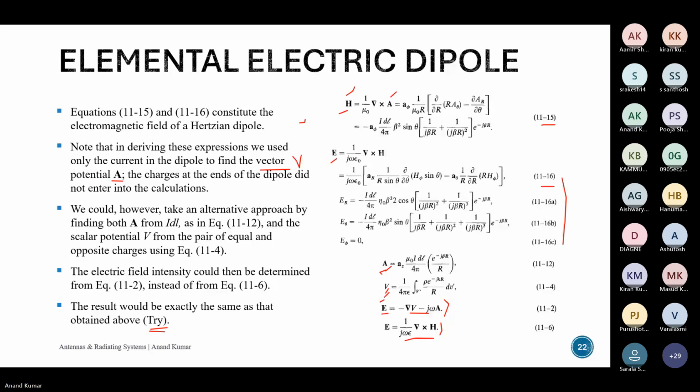They are designed to match for a wider range. Like you have a coax as your feed, which is usually 50 ohm, and then it matches throughout for all the frequencies. I think I've seen horn antennas in that frequency range. Okay. So horn antennas look something like this. So tapering is one of the methods which is used for wideband matching. You will see them on microstrip as well, or in antennas as well.